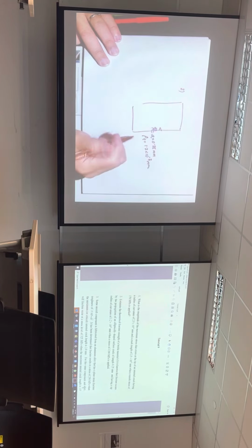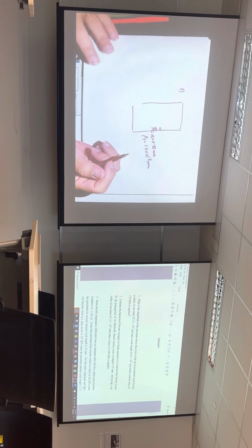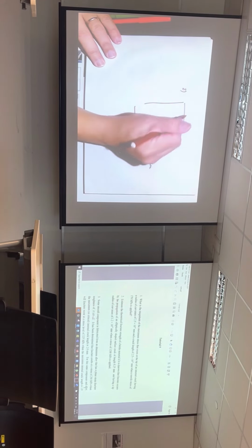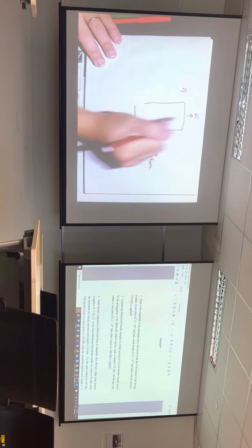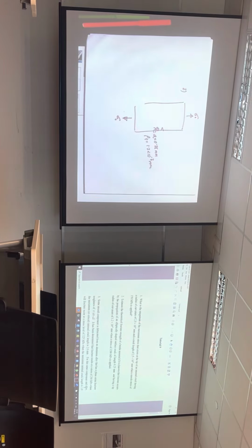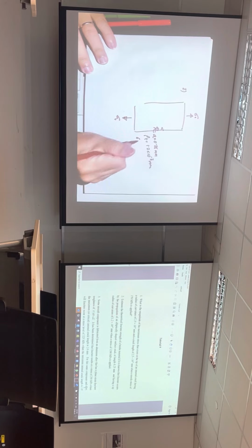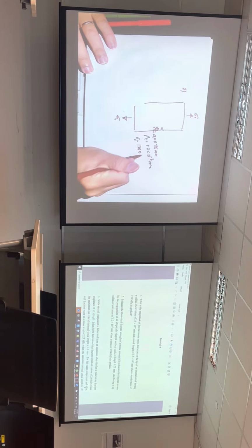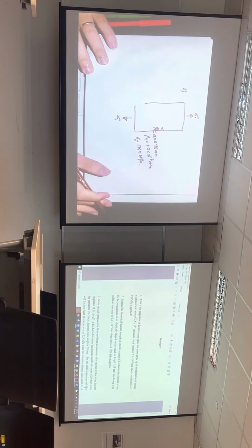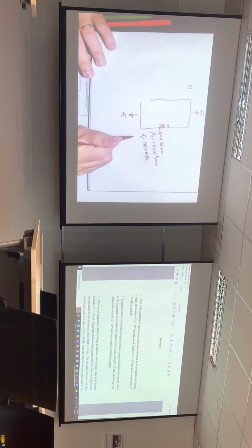When a stress of whatever is applied, this will be the stress applied, sigma naught. So it is applied generally throughout, not at the crack tip. You apply it on the body of the object. So sigma naught is given by 1200 MPa. Going back to the equation, sigma max equals sigma naught times 2.